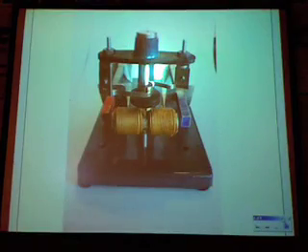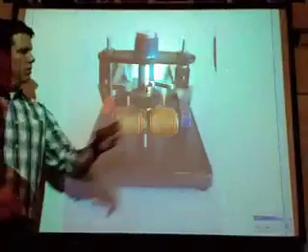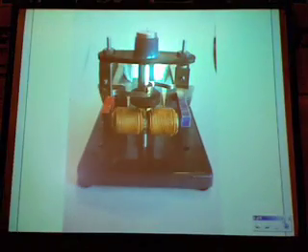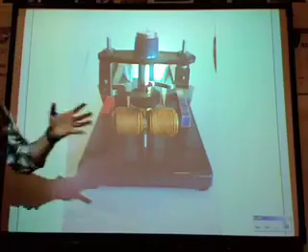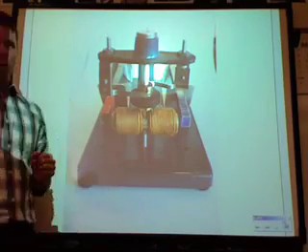Now the motor you're going to build is like this simple one I showed you just a second ago. It's going to switch on and off. You want to look for how that is accomplished. The motor that I want to show you now accomplishes its motion by switching its poles, changing its poles. In this real motor, this motor demonstrator, you can see now we've moved up to 2 permanent magnets. So now it's not just a matter of pushing and releasing, it's pushing and pulling.